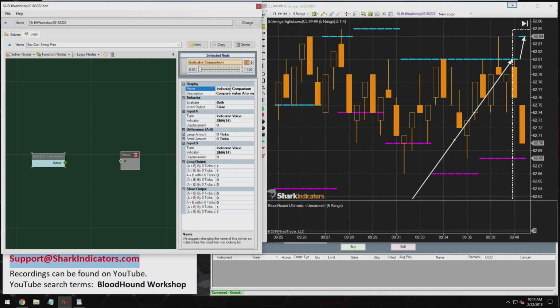So let's see here. This solver is going to be looking for expansion of the swing points. It's always a good idea to name your solvers so that you know what they are doing, because after a while, once you get a bunch of solvers on here, it's very easy to forget what each of these solvers is doing in your system. So always name your solvers.